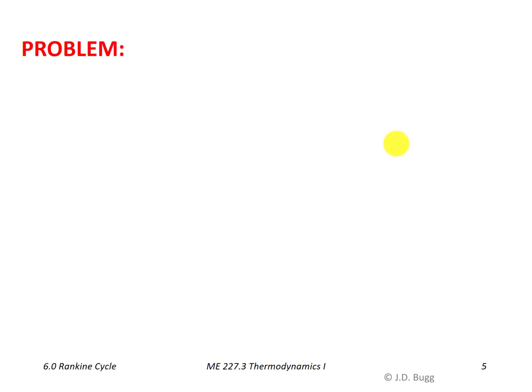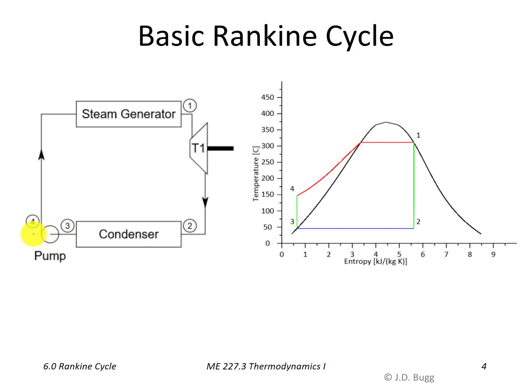Now there's still a problem with this. We've been talking about this side of the cycle, which happens over here, but there are also similar problems over with the turbine. Currently, we're asking this turbine to accept a saturated vapor and produce work isentropically, and its exit is a mixture of liquid and vapor. Well, that also is difficult to do. We want to, as much as possible, have these turbines working out in superheated vapor region. It's not always possible to eliminate completely the liquid that shows up in the turbine, but we certainly want to try to do a better job than this.